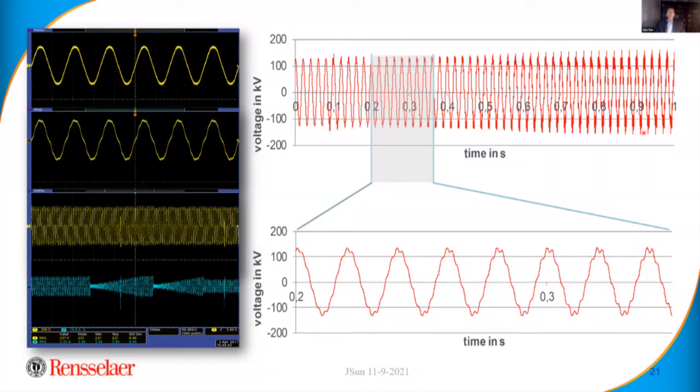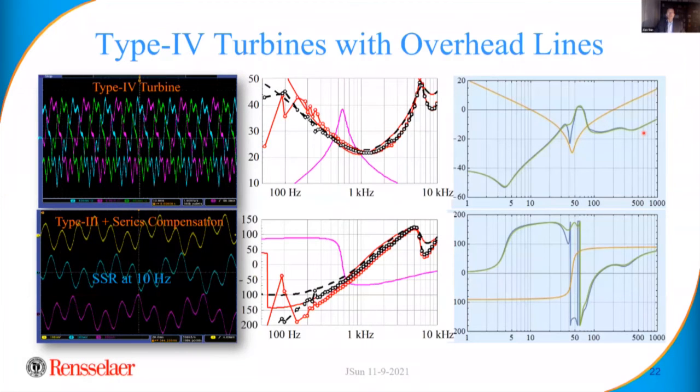How do we analyze that? Based on the frequency domain models, like this is the frequency response of the two impedances. We plot out the source impedance, the grid impedance, versus the turbine or converter impedance, magnitude response and phase response. For the Nyquist stability criterion, because we don't have to worry about right half plane zeros or poles, we can just simply look at the Bode plots and look at where the magnitude intersects, at those points.